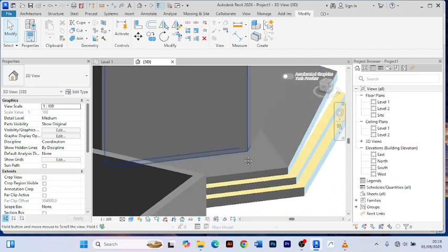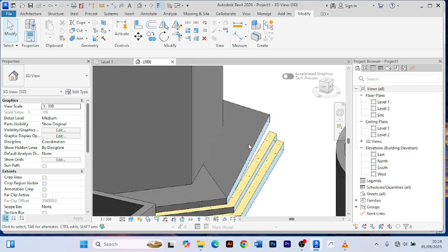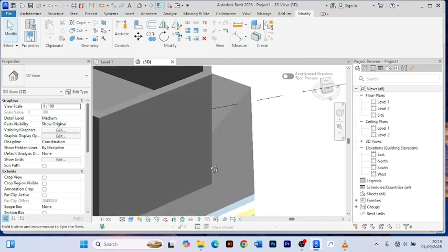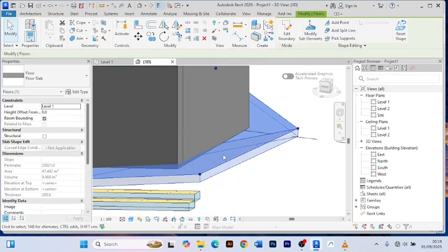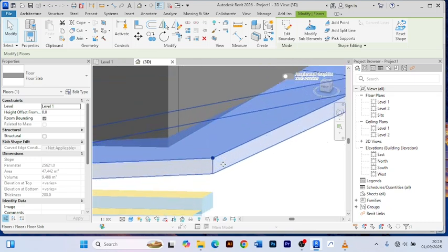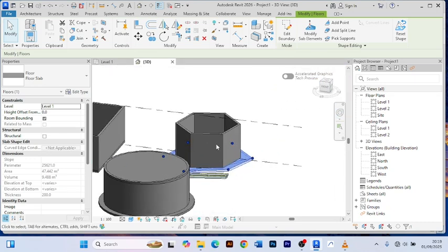This can happen, for example, when your landscape is not even. If your landscape is bending, or it needs another step down, you can easily play around with this sub element to modify the points, just like that. So I believe that will help us understand the floor tool or the slab tool in Revit.